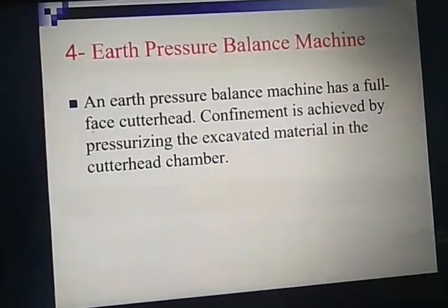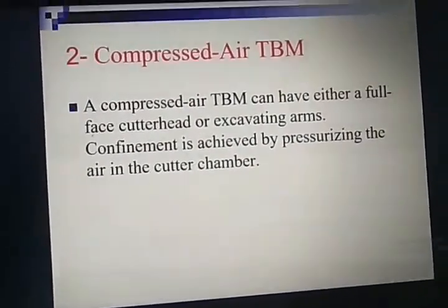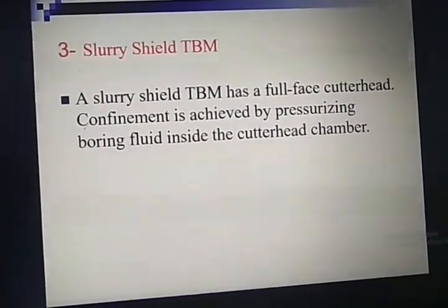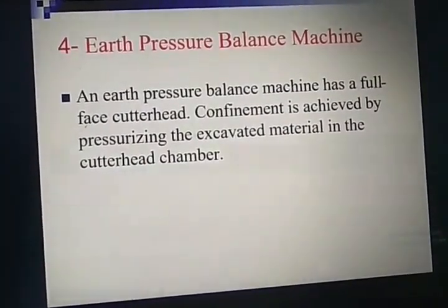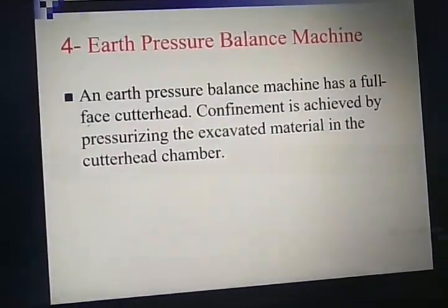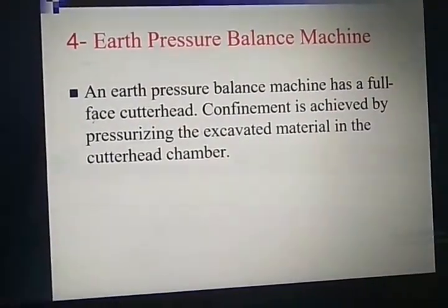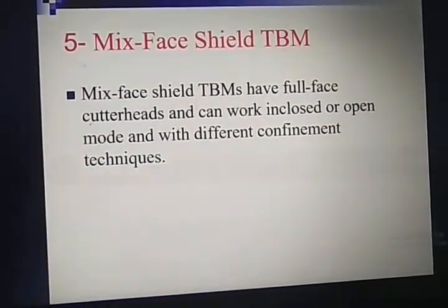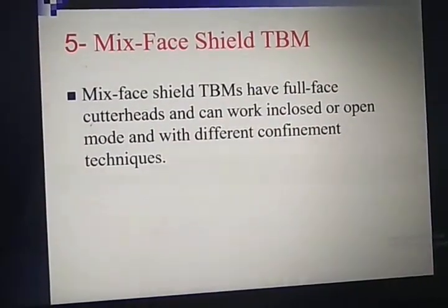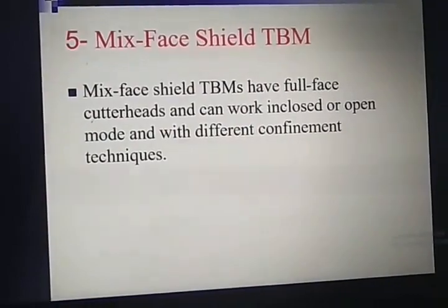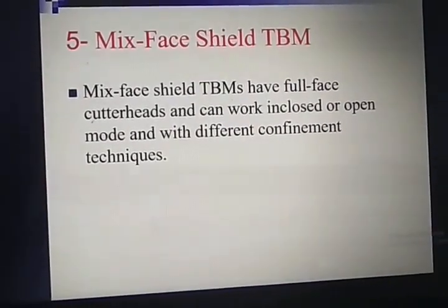First one is the air, then here the water or fluid we are putting, and whatever the excavated material is, itself we are putting into that one for the excavation. Mixed phase means mixed phase shield tunnel machines have full face cutter heads and can work in closed or open mode and with different confinement techniques.